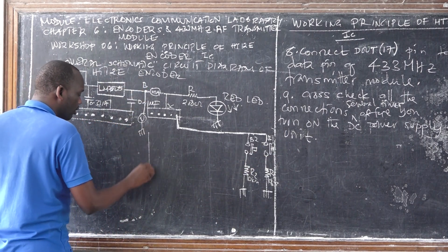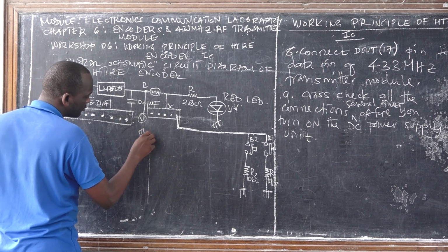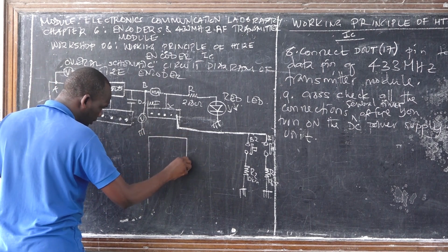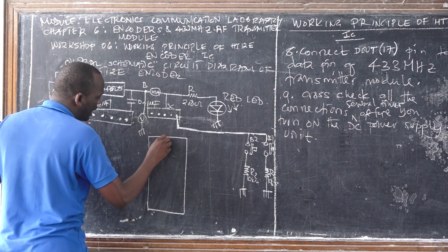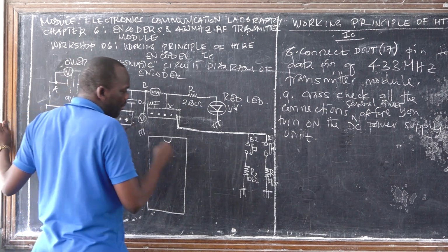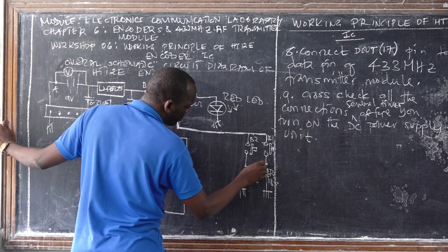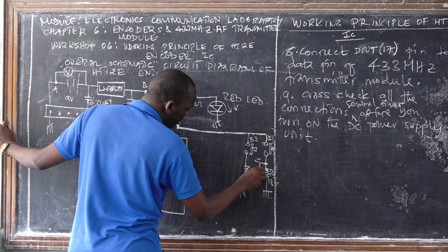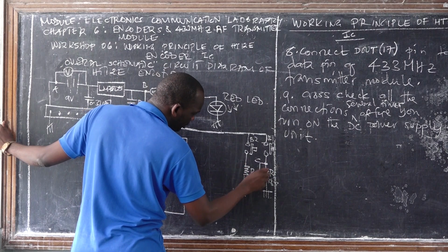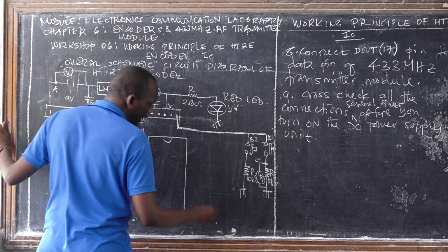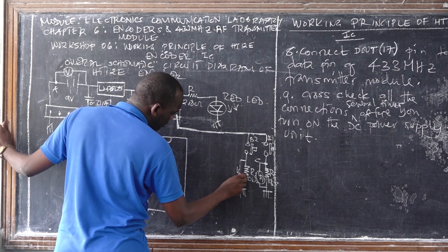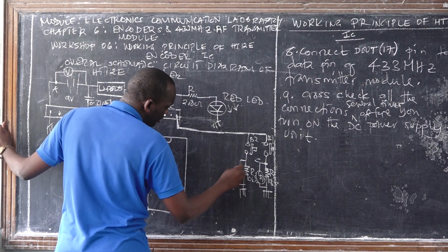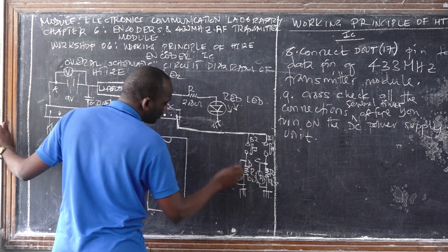Then we need to have our control unit. This is the HT12E encoder. But remember that here we have another testing point, which we call testing point C. What are we going to measure? At this testing point, the voltage VR1, across R1. So this will be the input voltage to the encoder. Also this one, it's VR2, and this is testing point D for the input.